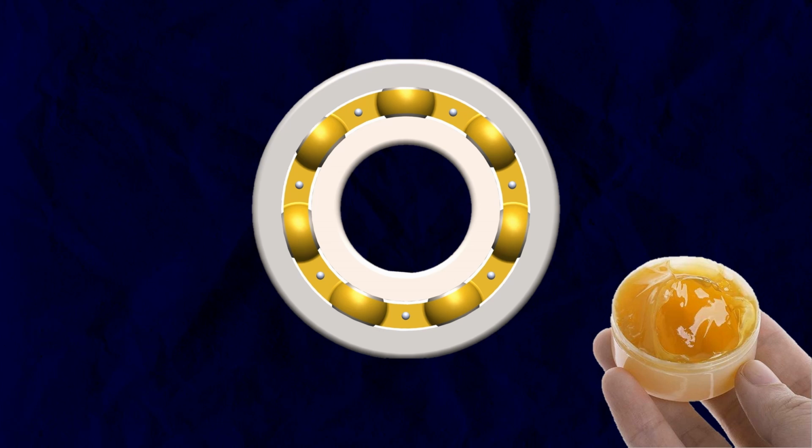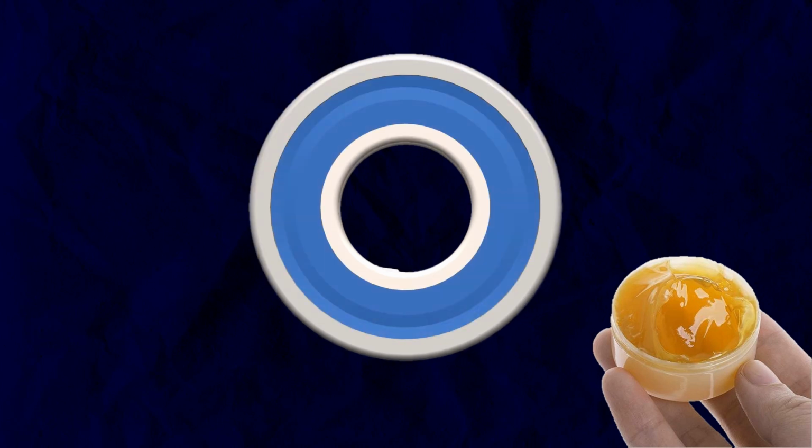And now to further reduce the friction, we can apply lubricant like grease. But at high speed, lubricant will not stay inside the bearing. It will easily be thrown out. So to keep the lubricant inside the bearing, we have to seal the ball mechanism with a cover, an integrated cover. Also the seal is important when the bearing is exposed to a dusty area. It also prevents contamination.